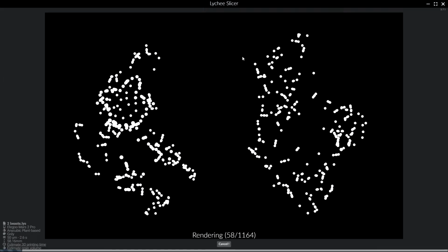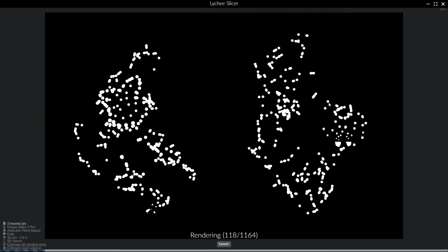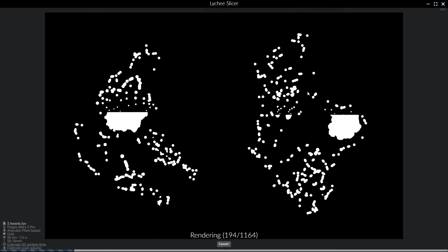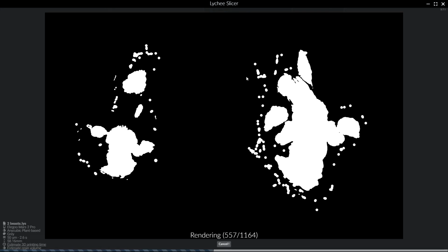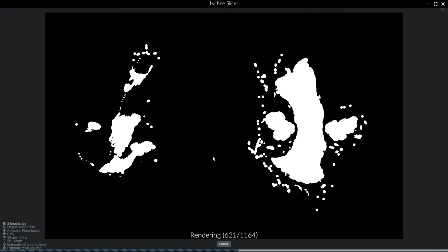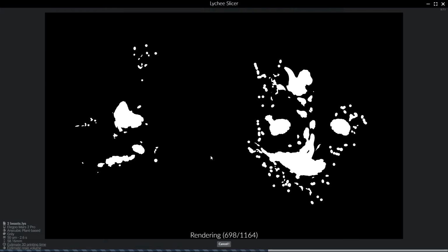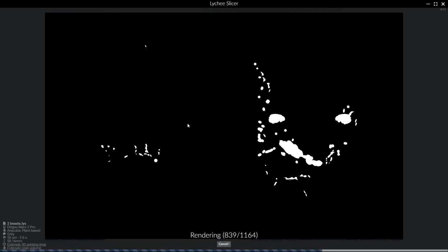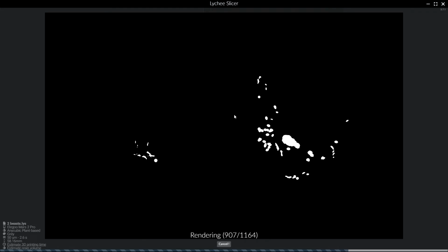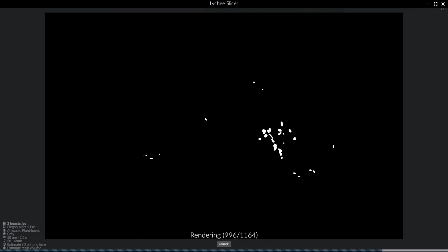And now it will process the model layer by layer, do a vertical slice that is just 50 microns thick. And while it does that, you can also check if anything looks strange. For example, if a huge blob suddenly pops out without there being any supports before that, you're looking at an unsupported structure that won't print right. Everything has to flow into each other in this screen.